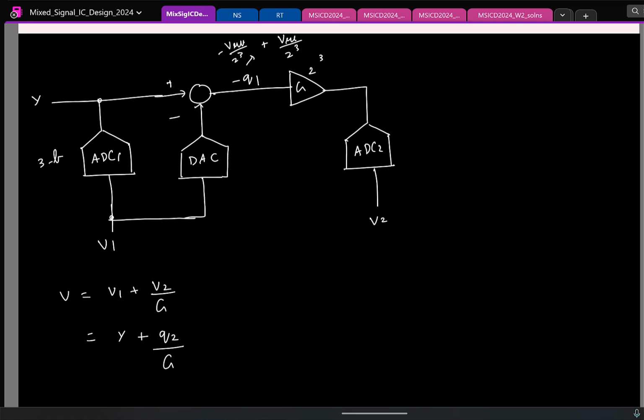If I increase the gain, I have 3-bit, but still if I increase, let's say I choose a gain of 10 power 6, what happens? From here it looks like it's fine, so what's the issue? If I use a gain greater than 2 power 3, what can you say about the signal swings here?